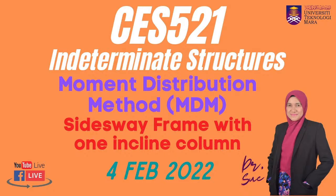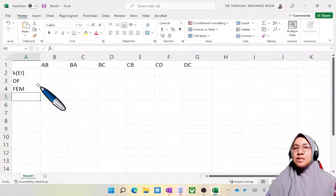So this is the first table. The first table we will focus on non-sway frame. The FEM will be calculated using the external loading only, because we have removed the delta from the system by putting an artificial support at C. The frame is now a properly restrained frame.